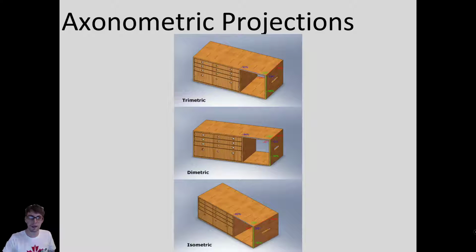Okay. Here are some axonometric projections. These are standardized isometric ones, and they have standard angles and standard ratios, so people in different fields will work with them and be familiar with them. Purely isometric, you have the offset x, y, and z to be the exact same angle here. So it's a balance between the three, but you can reshift this, and there are different standards, but we're not going to get into it.